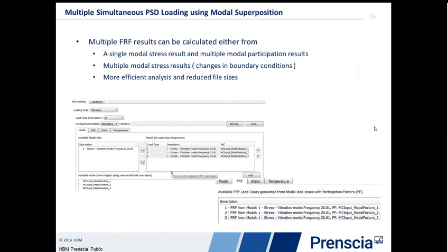The first tab is to manage this modal superposition. It brings in and pairs up the modal stresses from a finite element analysis with a set of multi-column modal coordinates. You'll have one of these sets of modal coordinates for each mode shape in your model.